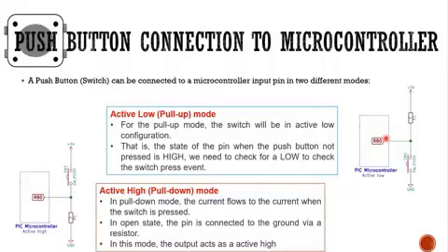to write to the microcontroller, we need to push the button so that the state changes from 1 to 0. So when it is 0, this means that the microcontroller will start to execute a certain function, okay? Because it will only become active when the value here becomes 0.